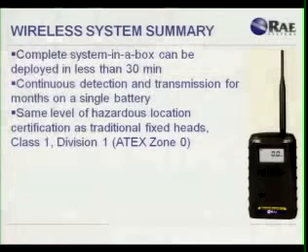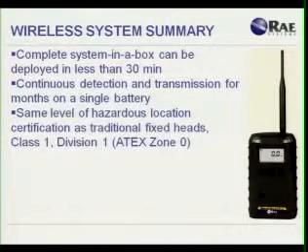Again, there's no compromise on the safety certifications. We have global safety certifications. There's no trade-off on a fixed system versus a wireless system. We have Class 1 Division 1 certification for North America, and we have ATEX Zone 0 and IECEx Zone 0 as well for international overseas locations. They're the exact same safety level as any fixed head you could buy.